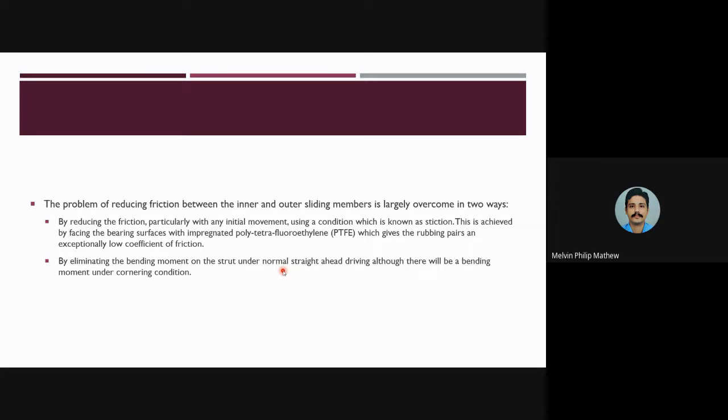And then comes the small camber changes. So they have discussed the camber. You know that camber is, when looking from the front, the inclination of the tire with the vertical. So when camber gains, you can see how the tire was hitting this coil spring of the suspension. When hitting the coil spring of the suspension, sufficient camber is negated, so there is no gain. When you are releasing it on the road, it becomes straight due to the striking of the wheel with the coil spring.